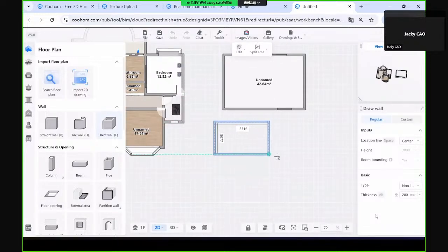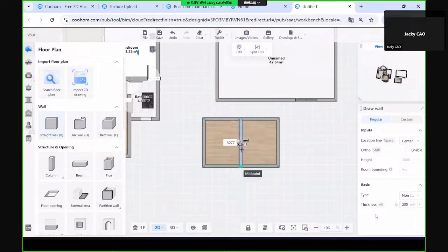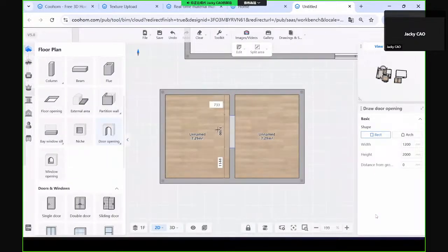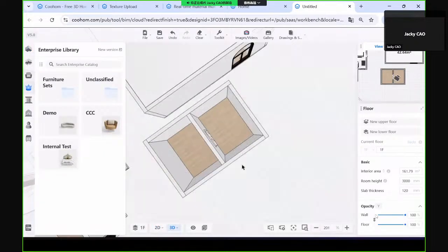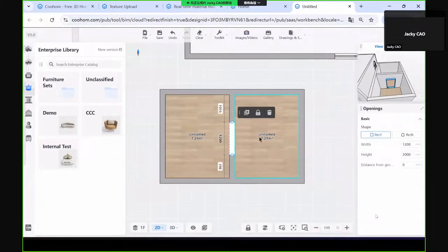For example, now it's time to draw. Still door opening. Still the same logic. Anytime you want to use any existing rectangle faces, you first place the biggest outer frame, then put the elements inside and use the frame to do the drawing, and then minus.